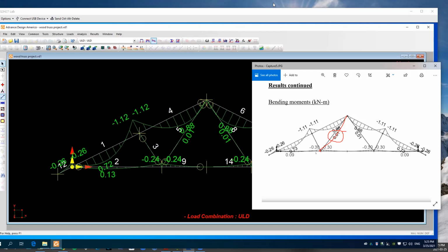Yeah. I mean, guys, that to me is like, wow, I know it's like 0.01, it's like peanuts, right? But the fact that the program will actually calculate the bending moment of the self weight of the member here, in other words, multiply the self weight by 1.25 and do the calculations. Don't you find that amazing? You see, look at here. So that means that we basically have the same member here, and we probably have about the same length. You understand? That's what that tells me also.